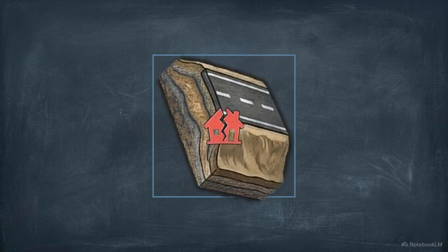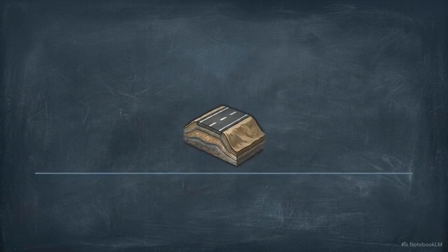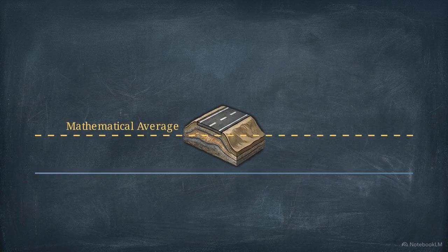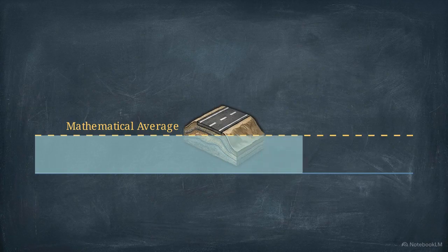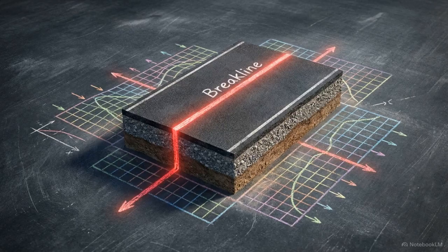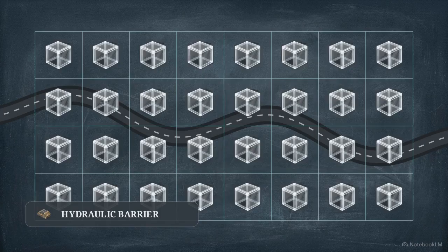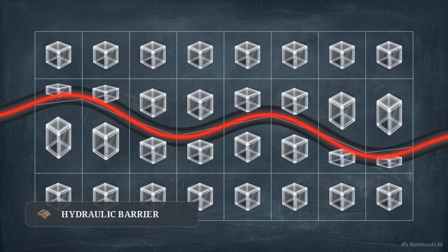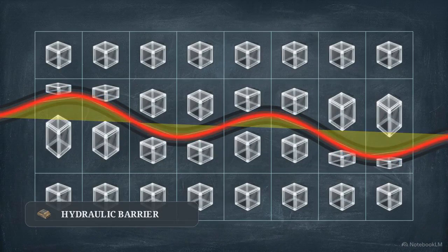This introduces a specific failure point. If a raised road bisects a large computational cell, the cell's mathematical average will artificially flatten the road, allowing digital water to pass through what should be a barrier. Engineers fix this manually using break lines. By drawing a rigid line along the top of the road, the software forces the computational cell faces to snap perfectly to the hydraulic barrier.